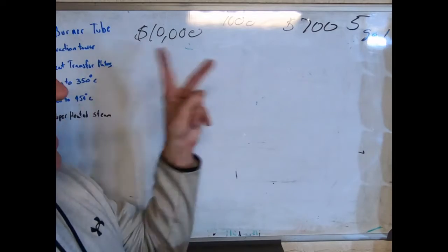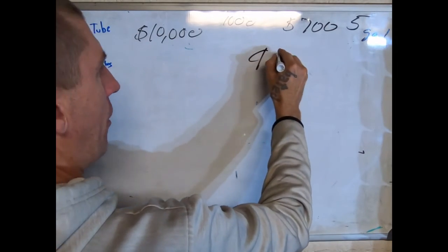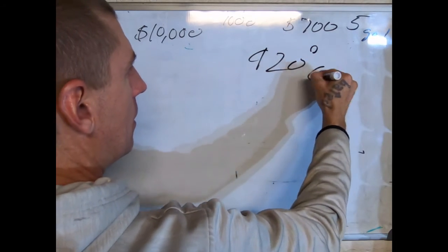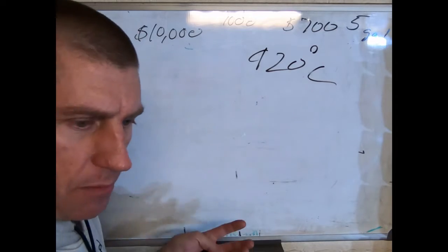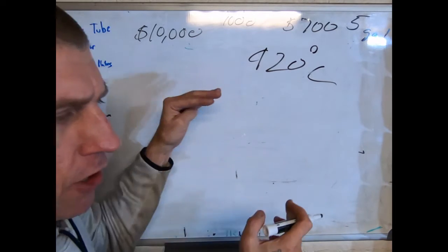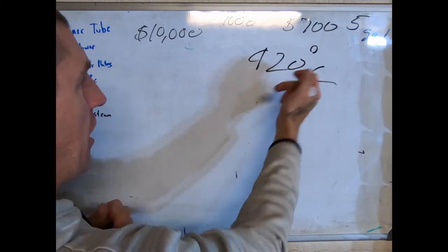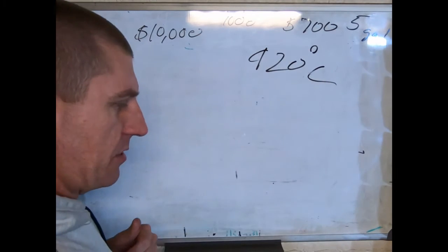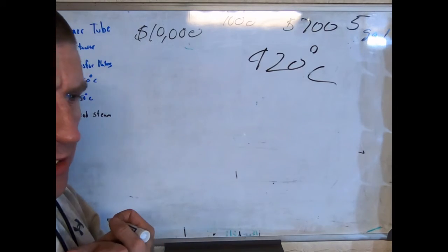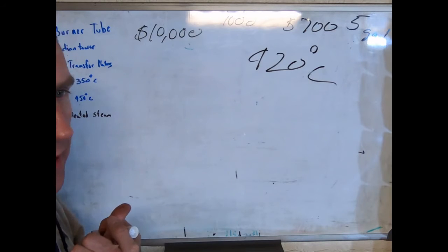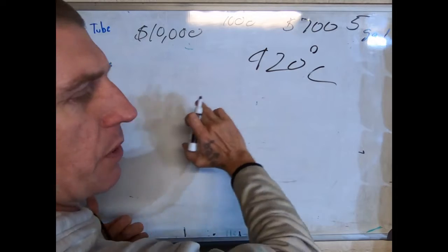There's two things that can happen to this oil. If oxygen gets into it when it's at 420 Celsius, it gets this carboxylic acid buildup that just destroys the system. So you've got to have an inert gas layer over the expansion tank. If you get it over 420 degrees Celsius or so, you destroy it. And we all know how temperature specifications and regulations work out in the desert. We need something that can just be beat to death. Like you almost need liquid metal.